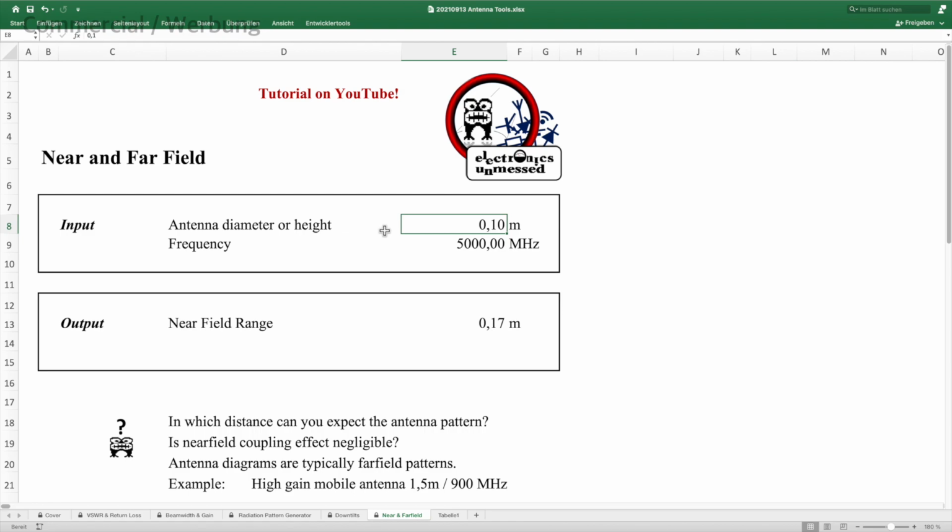We are having a parabolic dish antenna with a diameter of 70 centimeters, which we use to receive a 5 GHz signal. As we know from what we said before, high gain antennas have a narrow beam width. Our question is now whether the narrow beam can prevent us from problems with an interfering transmitter which is located close to it.